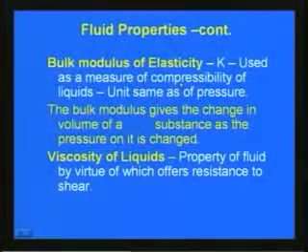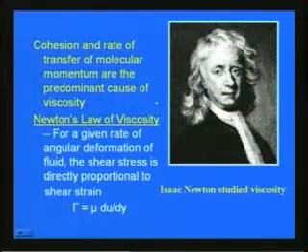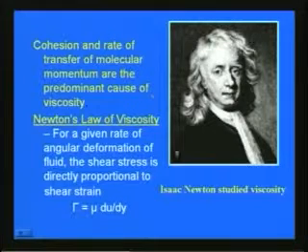And another important fluid property is the viscosity of liquids. This is a property of fluid by virtue of which it offers resistance to shear. So, this viscosity was studied by the famous scientist Isaac Newton, and he observed that cohesion and the rate of transfer of molecular momentum are the predominant causes of viscosity, and he derived Newton's law of viscosity.